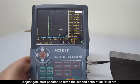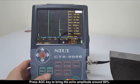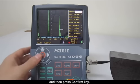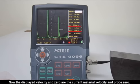Adjust gate start position to hit the second echo of R100. Press AGC key to bring the echo amplitude around 80%. And then press Confirm key. The screen prompts completed. Now the displayed velocity and 0 are the current material velocity and probe 0.